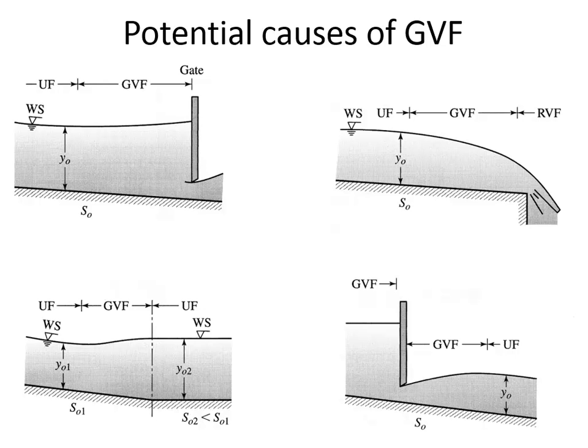The other way around. So a hydraulic jump forms when you've got supercritical flow. So here's supercritical, and then it transitions to sub. So that's when a hydraulic jump forms. And one of the times that you can have supercritical flow is if you have a gate, but the slope was mild. And that's what we saw back in the lab. We had a mild slope, and the flow underneath the gate temporarily made the flow supercritical.